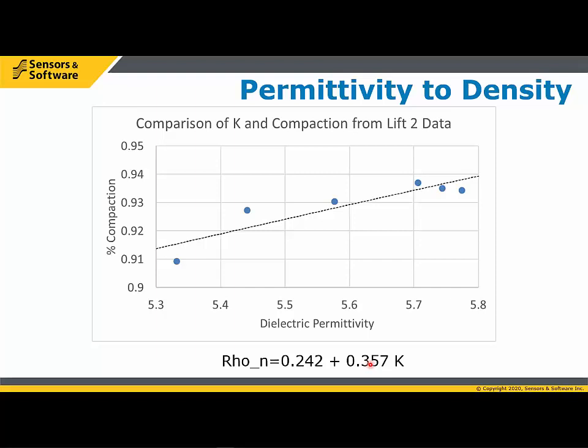So the calibration in the field is this estimating the permittivity to density, and there's a number of ways this is being looked at now. Some lab measurements to do this and so on. But it's the weak link if you want absolute densities. But if you are looking at relative variations, then you get a really good handle on that from looking at the permittivity. And there are empirical relationships that convert permittivity to density, but they may not be exactly right for a particular site.